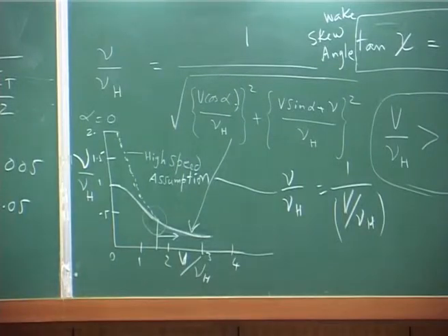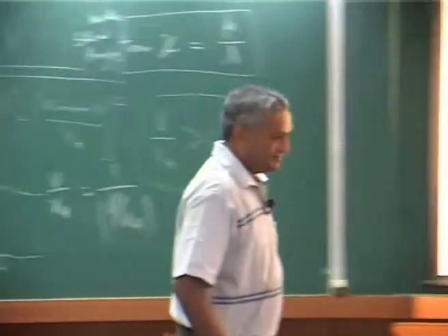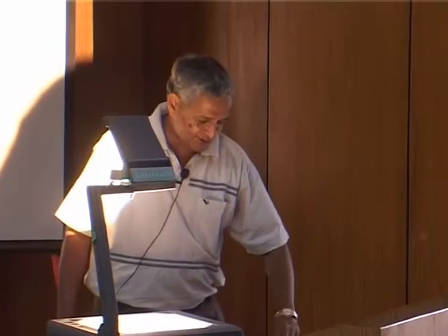All right. Now the question is, the rotor behaves like a circular disc. For a circular disc, we assume that the inflow is constant everywhere, but that is not true. There will be substantial variation in the inflow over the radial as well as azimuthal location. Then you have to have a theory, but I will briefly give this only as history. What we are going to do is follow,